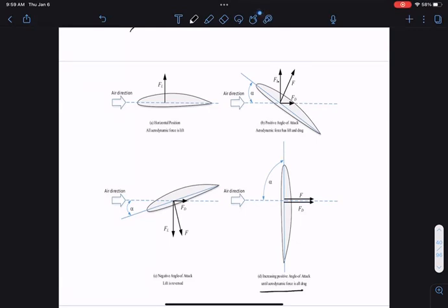Okay, so this is an important operation, just to keep in mind. We have angles of attack. Sometimes you have an angle of attack of 90 degrees. That may not make any sense to you, but this is where we want no lift force. It's important to be able to stop the blade. A lot of the first generation wind turbines failed because they couldn't really do this, and then you have blades flying off turbines.